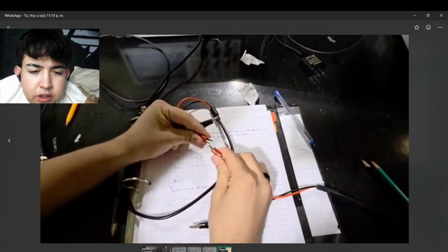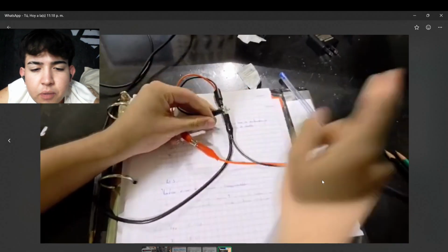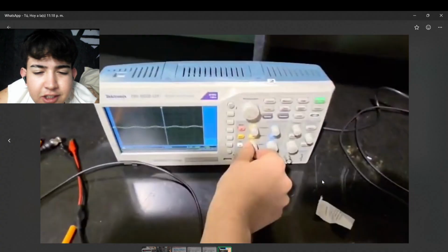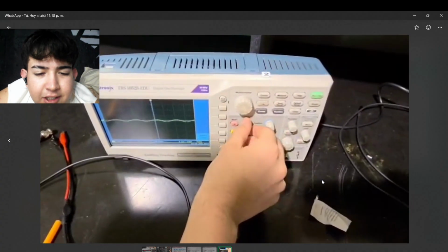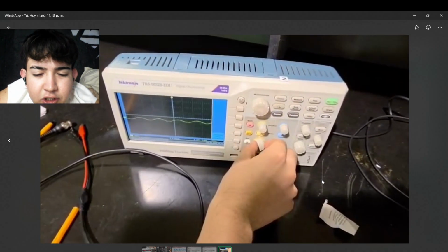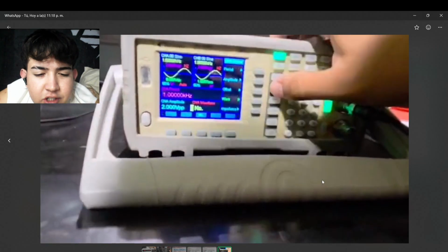Step 1. Oscilloscope power up and connection installation. The oscilloscope was powered on and the probes were connected to channel CH1, ensuring correct polarity when connecting them to the oscilloscope's test point. Step 2. Signal observation and signal calibration.